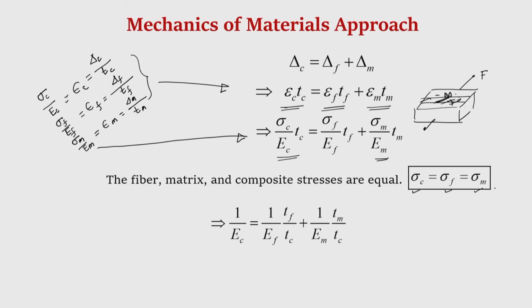Stress in the direction 2 is same, but unlike in the longitudinal Young's modulus, here we did not make any assumption in direction 1. In direction 2 the stresses are same. Whereas, in the determination of longitudinal Young's modulus, we made an assumption that the strains in direction 1 were same. This is reasonable only when the fibers are perfectly spaced.